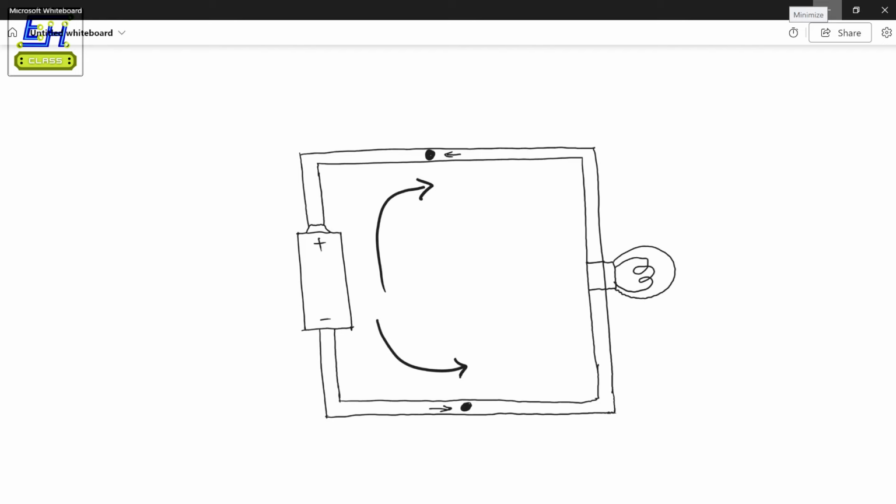So these are the electrons moving through the conductor. According to this logic, electrons actually travel the entire circuit. But this is not what happens, because the actual velocity of electrons, known as drift velocity, is very, very small. It is barely enough for the electrons to move, let's say, a millimeter. This is actually an exaggeration, but they barely move from their original location.